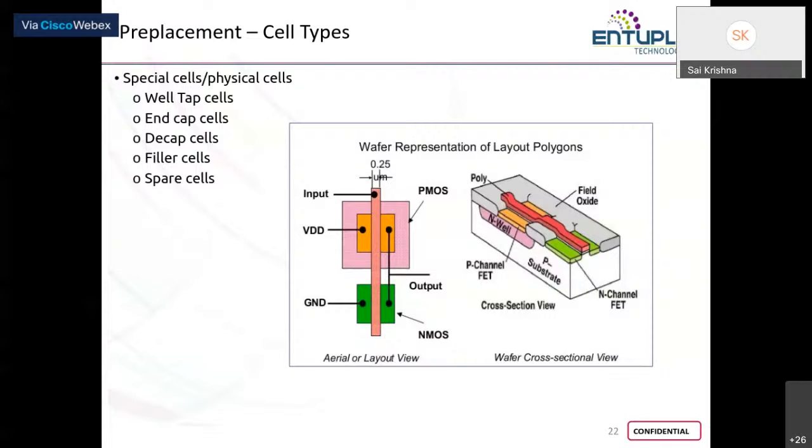Heavy current flows through your device, damaging it, right? To avoid that, you add a shunt resistance in such a way that your gate gets biased and takes in only the required amount of voltage and current, and the remaining excess goes through the shunt resistance to your ground.